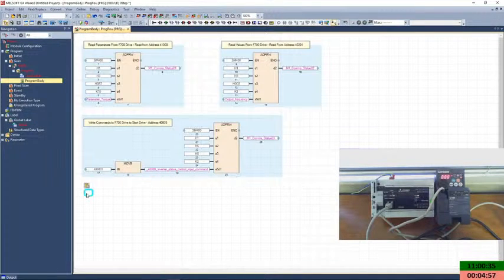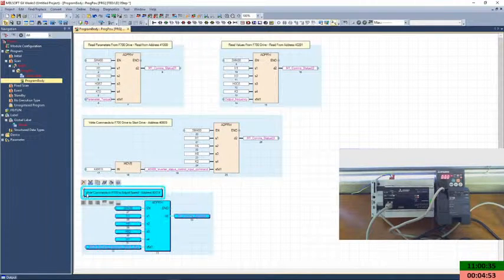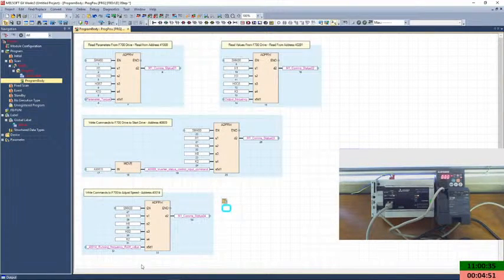Okay. And then the next thing we are going to do is write to the speed, to control the speed. So H6 again, we're writing to that address, the next two addresses, and we are writing to that register in the PLC. So D112, as I spoke. So you'll use D112 to set the speed. Okay.